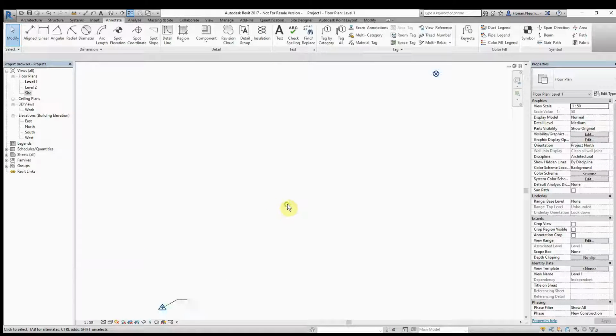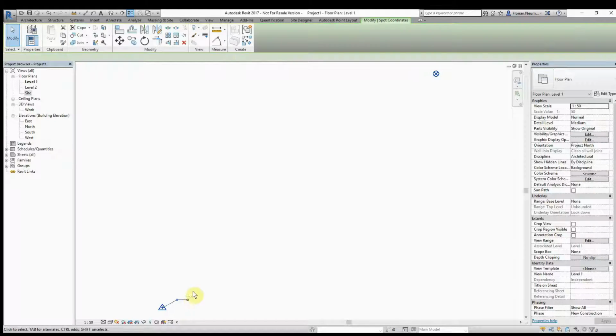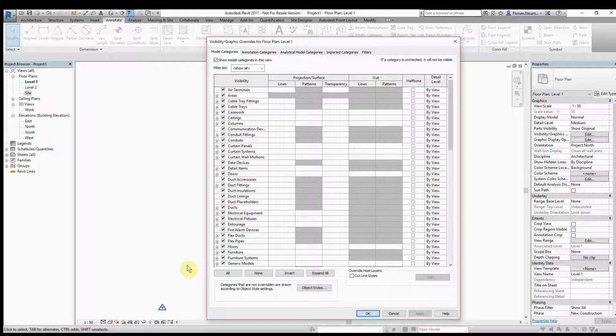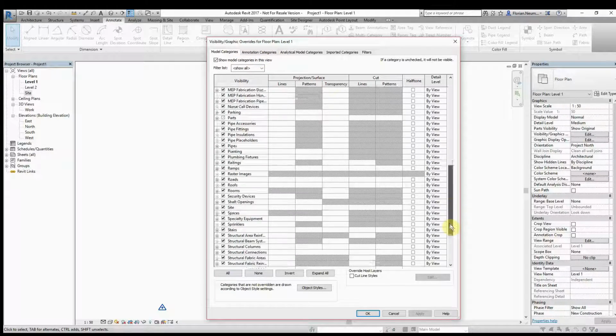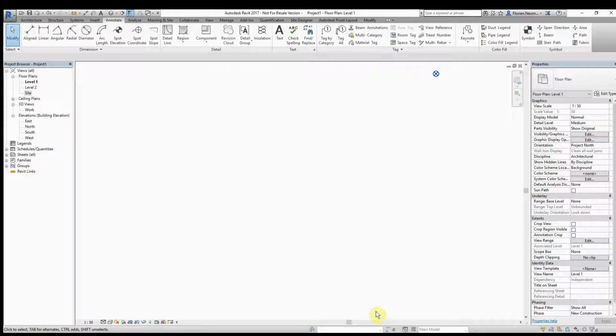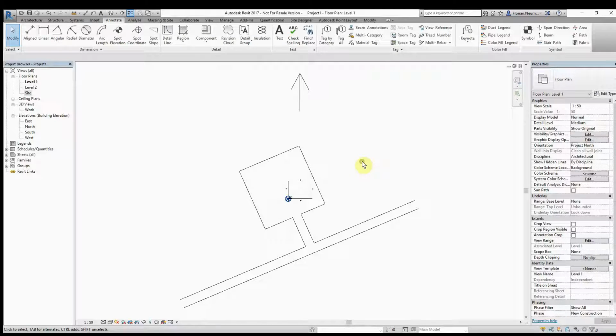Okay, great, fantastic. So, how do I now, in my plan, do a zoom all and zoom to my model? For this, I just need to switch off my survey point, and I can do this somewhere under my site. We can go here under my survey point, quickly turn my survey point off, hit OK, gone, and now when I double click, everything is back up and running.